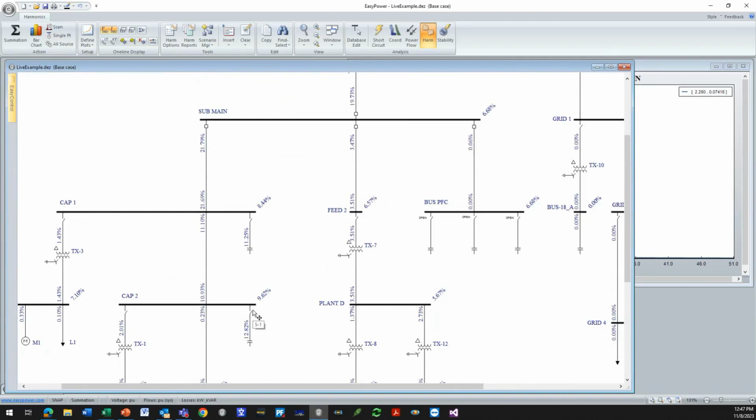So you can see what I'm doing. I'm just changing statuses, and these would be individual cases in your study. You would say, what would happen for this system condition with these 2 banks on and all 3 of these off? One row of your table would have these voltage distortion answers. But that doesn't tell you where the problem is. It just tells you the distortion is high.